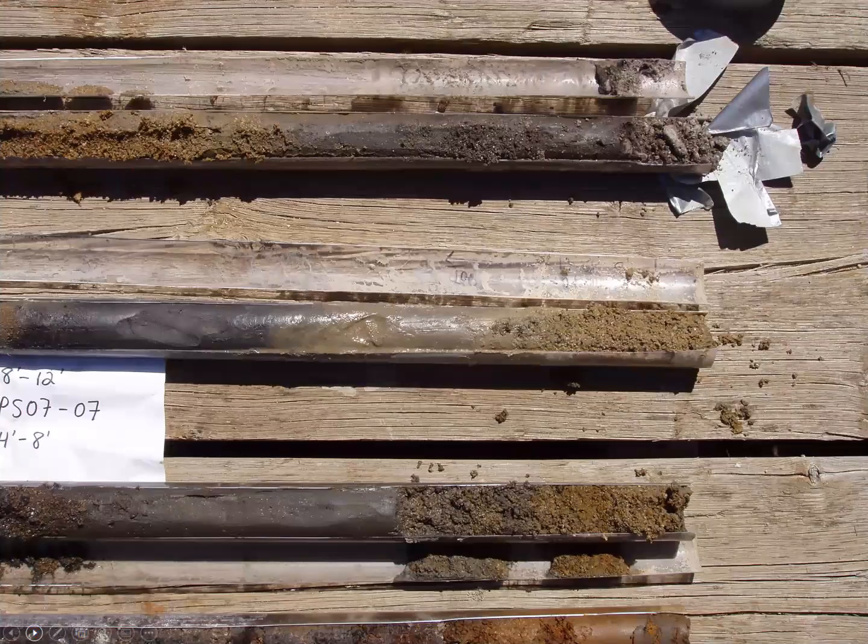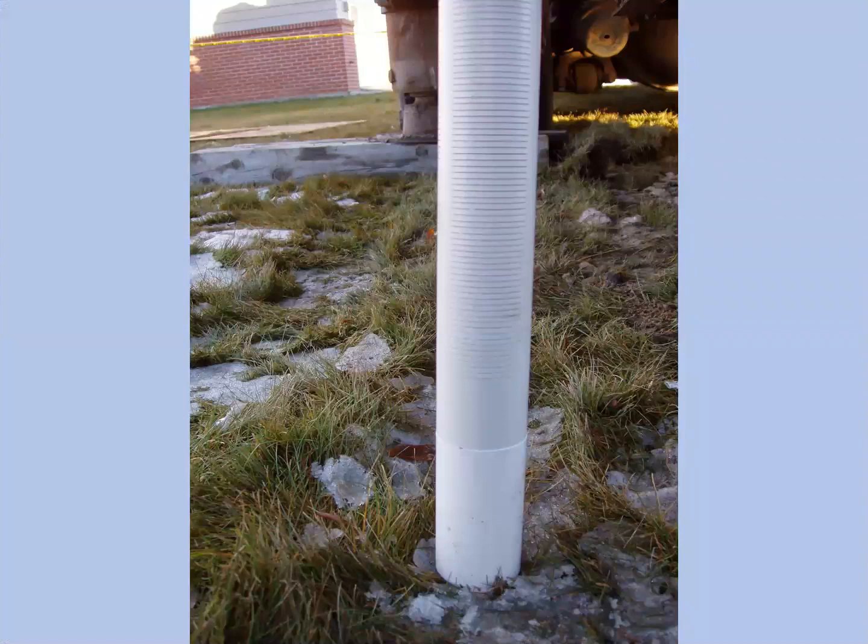So here's another way to drill, and these are split spoons. You can see up here a sandy section, but then right here you can see a very tight clay section. So this would be aquifer material. This would be what we call an aquitard. In other words, water really doesn't flow through it, and it can separate those aquifer materials into unique aquifer units. And just a picture of a well screen. That's the area where you would actually pull water into the well from the aquifer.